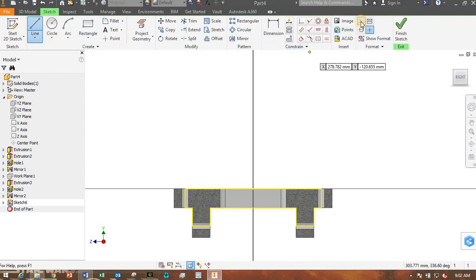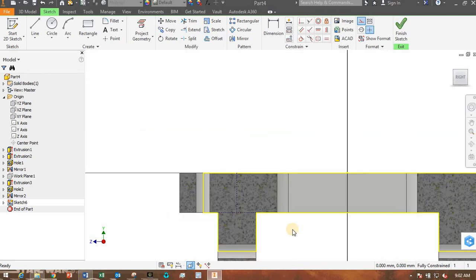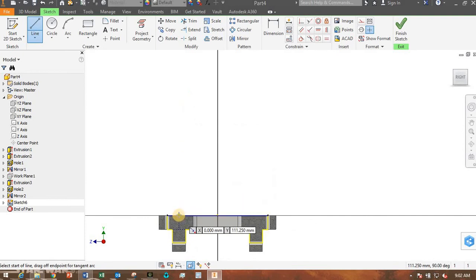And I'm going to make some construction lines. Let's make one construction line that goes from here to here. Now let's make another construction line that starts in the middle of this. There's the middle point, and it goes up here. There it is. So I know this point right there is in between here and here at all times because it came from the middle of that line. Alright, I can turn the construction line off, and let's sketch generally.